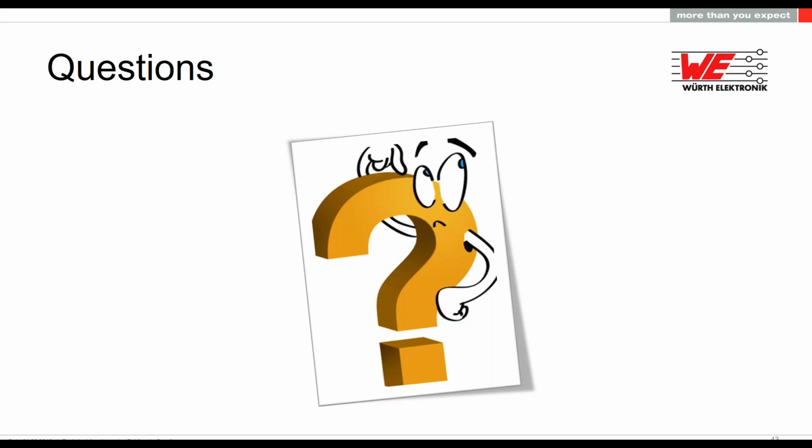Okay, what do we have else? There's a comment from a participant. What I missed was a comment on the underloading of connectors. According to my understanding, they oxidize with time and lose contact. Oh yeah, so I understand that you have been missing that, but I kept it out on purpose to avoid misunderstandings, because here we are really focusing on the derating. So in the overload of the part, we don't want to bring it over the maximum of what it can do, to have no negative impacts on the part.